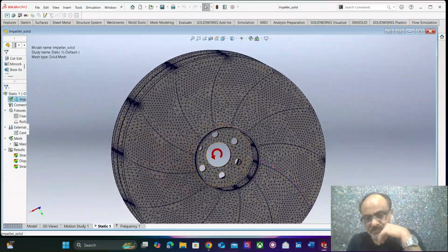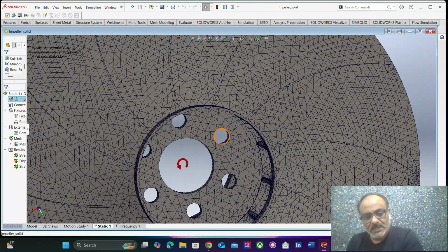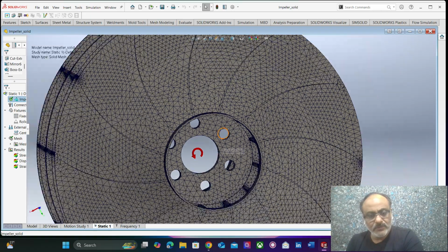Now we are going to apply the boundary conditions. We know that the shaft is going to be connected to these bolts, and these are 42 mm dia. So now this should be constrained. For the constraining mechanisms, we have 3 translations and 3 rotations. Any object, when it remains static at the same position, that is at the origin, is at a state of rest, which is 0.